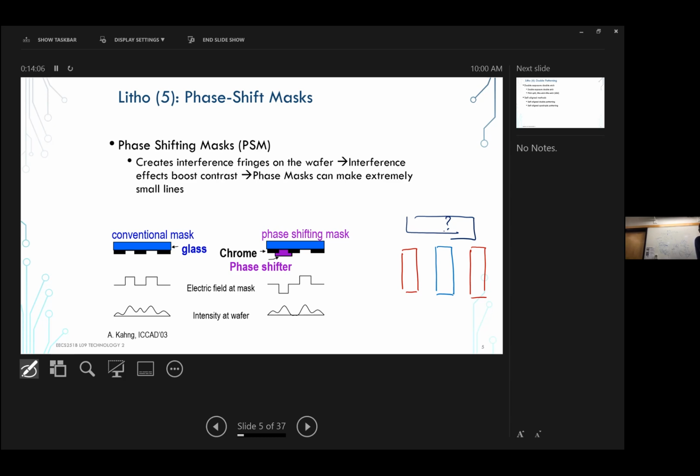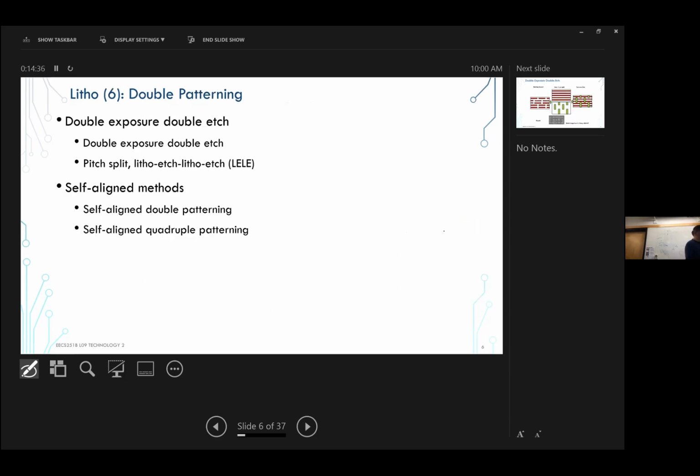Design rules are often confusing. You know, when you encounter that design rule error, it will refer to something like a coloring error. Now, you know what is going on. If you don't know the root cause, what is the coloring error here? Or graph coloring error, and so on. So I will not dive into that much more, but this gets more pronounced when we get down to double patterning.